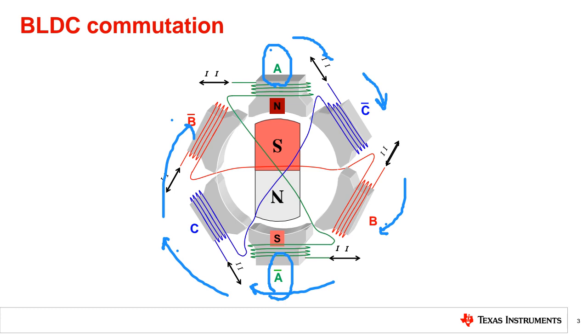While the brushless DC motors avoid all of these issues. What are they? Compact construction, spark problem, brake problem, lifetime, service time, EMI radiation. Brushless DC motors avoid all of these issues. It does require a more complex motor driver circuit to be able to properly commutate.